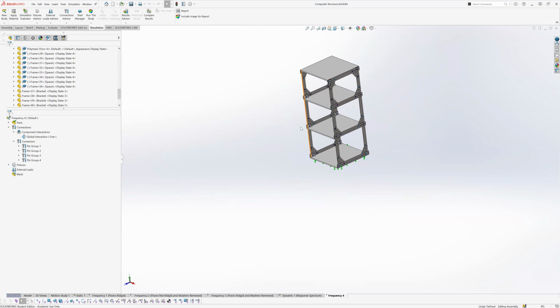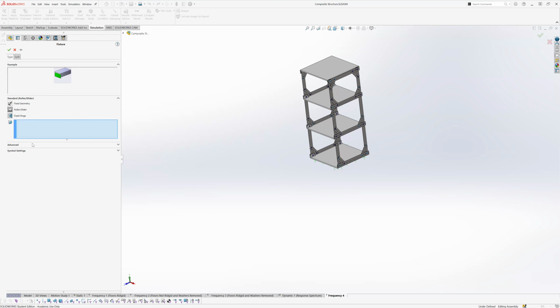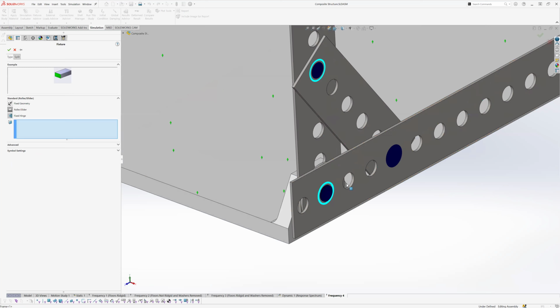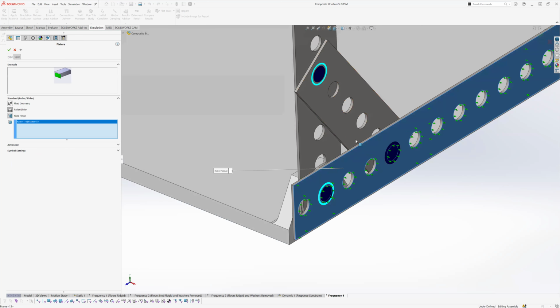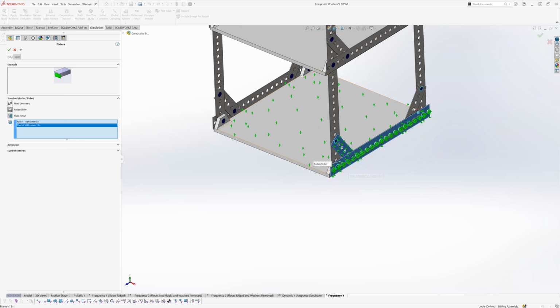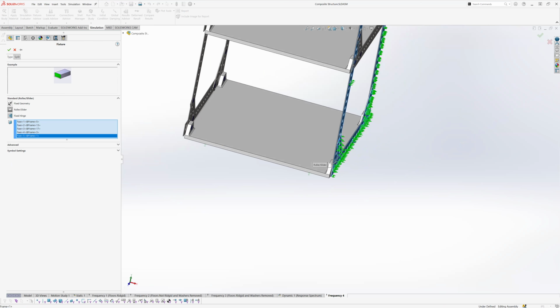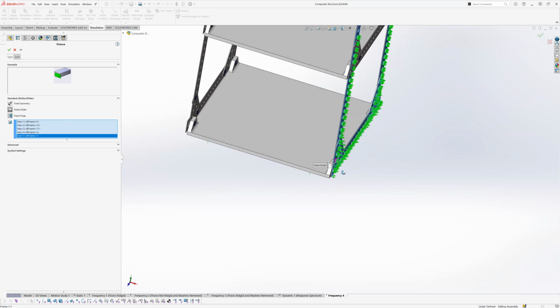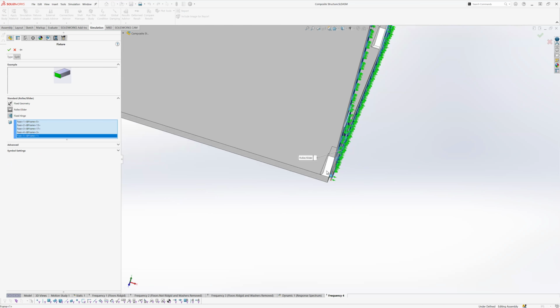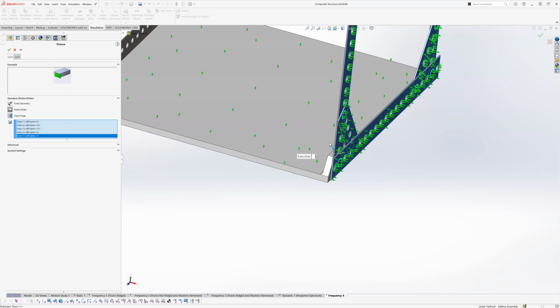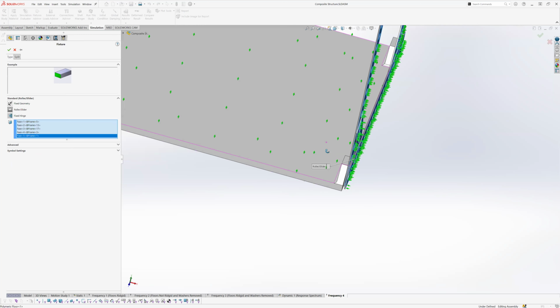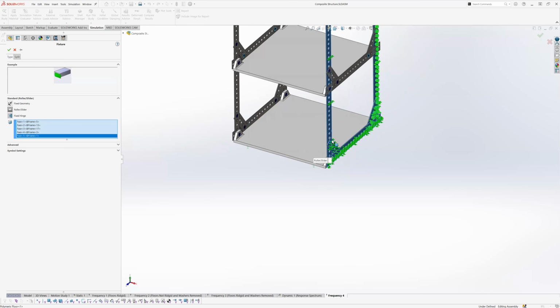So what we'll do here, and again this is going to be a little bit tedious as well, like the pin connection, is go to fixtures now. Obviously, we have our fixed geometry, so now let's go ahead and do our roller slider. For our roller slider, pretty much what we'll do here is go here, here, here, here. Now I'm selecting the outside of this instead of the inside. It doesn't really matter too much, but since this is rigid anyway, I just figured the outside would be a little bit easier to select, and sometimes it's as simple as that.